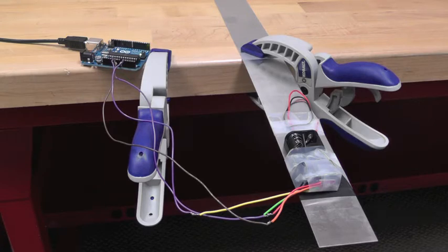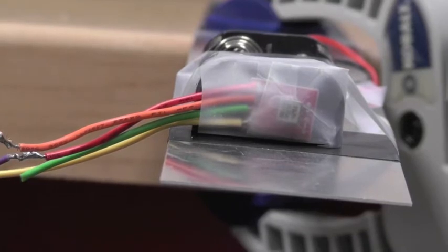The metal arm that you see will be used for securing the accelerometer and providing motion during data acquisition. The new device that you'll be using, an accelerometer, is a sensor that measures acceleration via changes in voltage output. This particular accelerometer is a single-axis accelerometer, which means it must be mounted in the direction of acceleration. You can also find triple-axis accelerometers, which measure acceleration in all three directions.